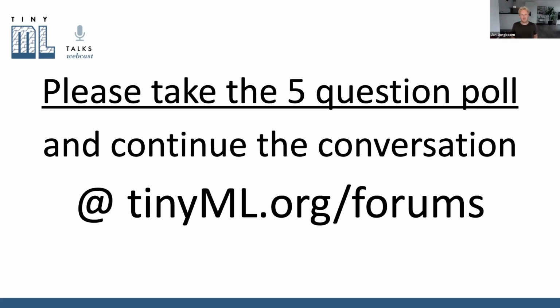Driving a radio is really expensive, right? On cellular, especially if you go from deep sleep, you need to make a connection to the cell tower, do this kind of handshake, and then send data over. You're basically bursting for 30 seconds or so to set that connection up, and in that time you're probably drawing about 100 milliamps for the 30 seconds. So you're burning through your battery really, really quickly.